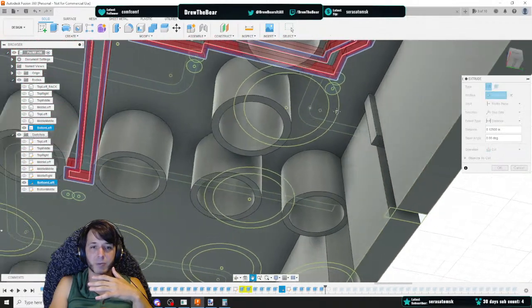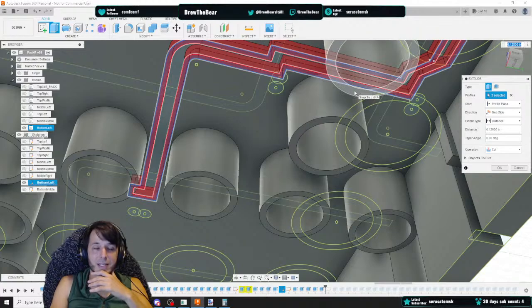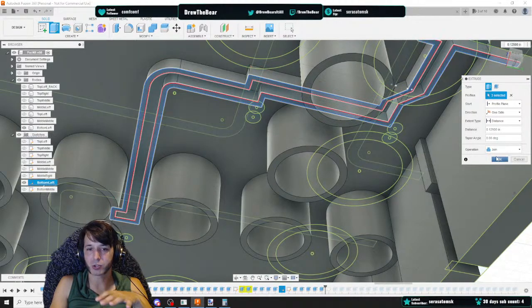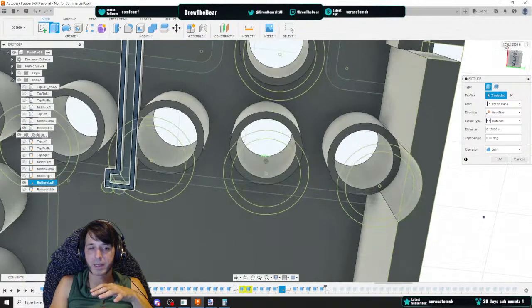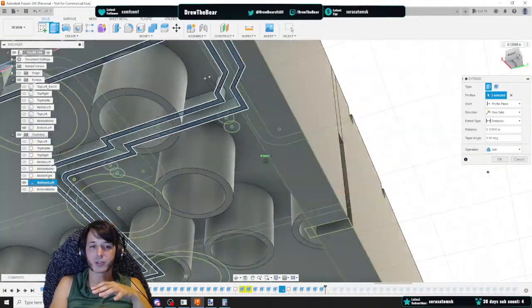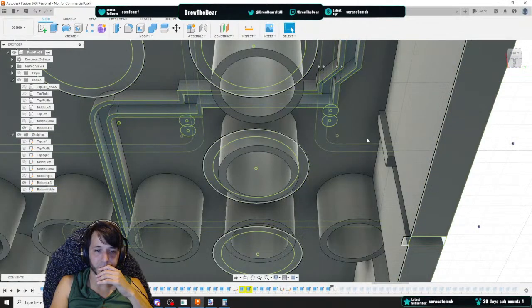It's colliding with something. But what it's colliding with is some of these rods, some of these LED port tubes. And you want to join to those sections. You don't want to cut. So we're going to change this to a join. As you can see, now I have this trench that will be created here. So we're going to join that.